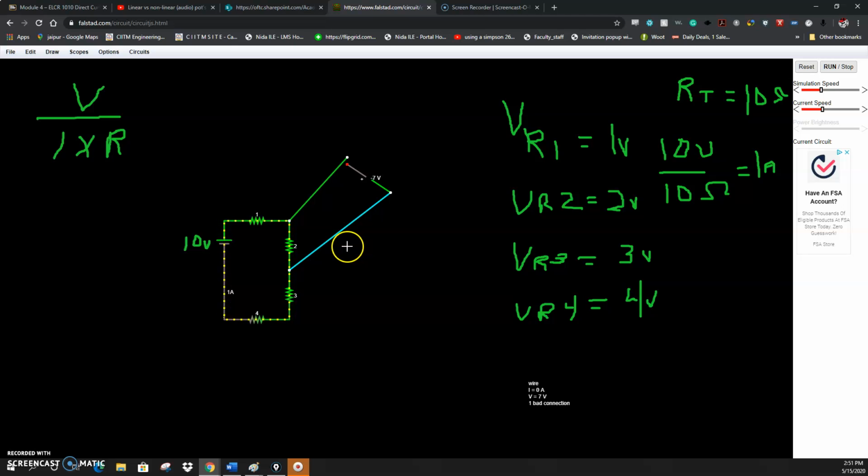And we're measuring -7. I see why I missed getting my lead connected right here. So I'm going to hit escape where I'm not drawing, and move this lead back to my target. There we go. Now we're measuring 2 volts. So that was a whoopsie on my part for not getting that directly across.